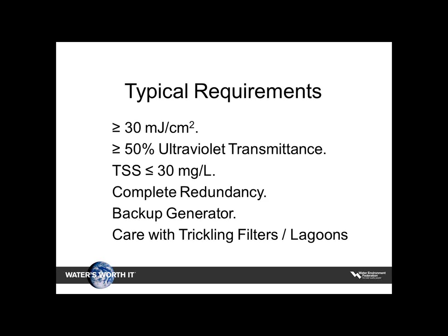You need to take particular care, again, with lagoon systems or with trickling filters, because that 30 suspended solids you're probably not making, if you were putting it behind a trickling filter or a lagoon as a retrofit on something like that. I would imagine most agencies would ask for a little higher number for the dose to ensure effective kill, mainly due to the variability of the suspended solids coming off these things.